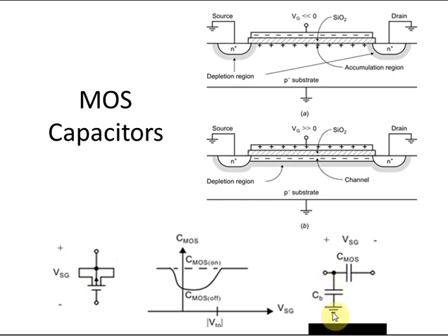So again, just to summarize all this about MOS capacitors. MOS capacitors can be used in lots of different ways. Basically, for me anyway, a MOS capacitor refers to just making use of that gate oxide as the isolation layer, the insulation layer between two plates of the capacitor. And you can do that with NMOS, PMOS devices in various operating modes. But regardless, a good thing about it is that you're now making use of the thinnest and most tightly controlled dielectric available in any manufacturing process. And it's the gate oxide.